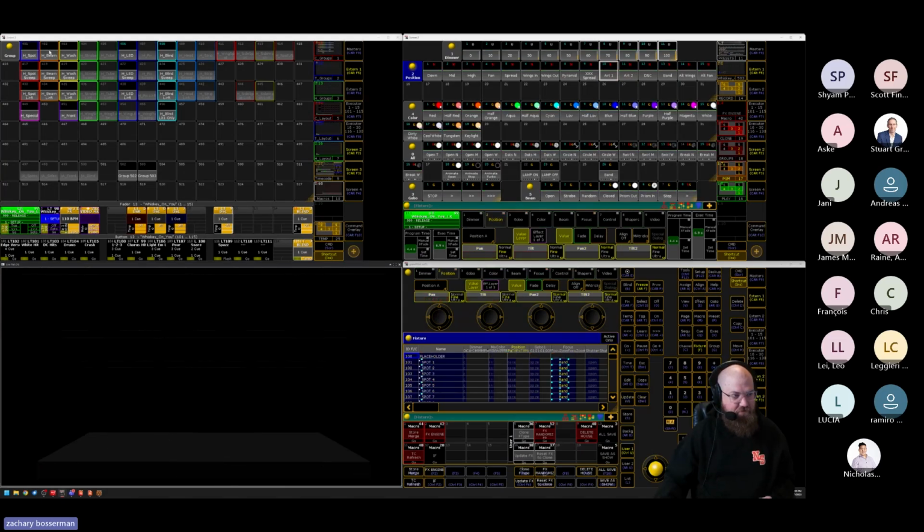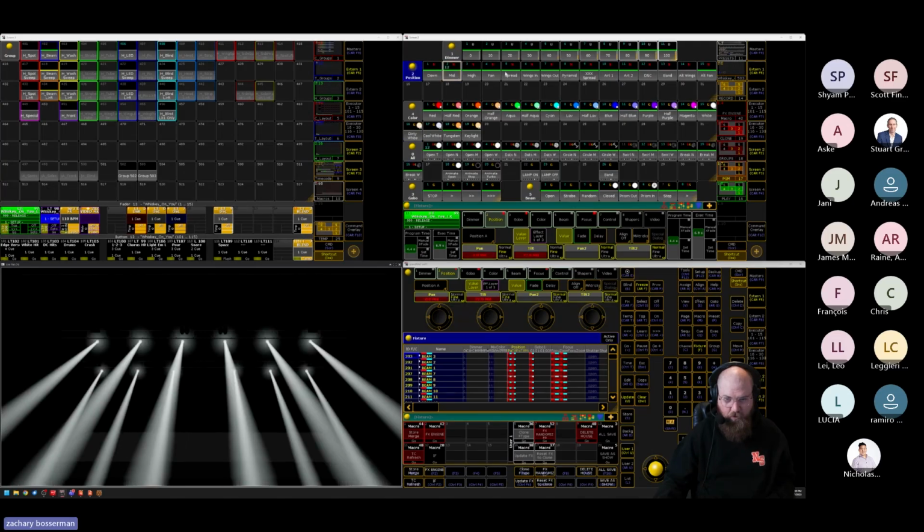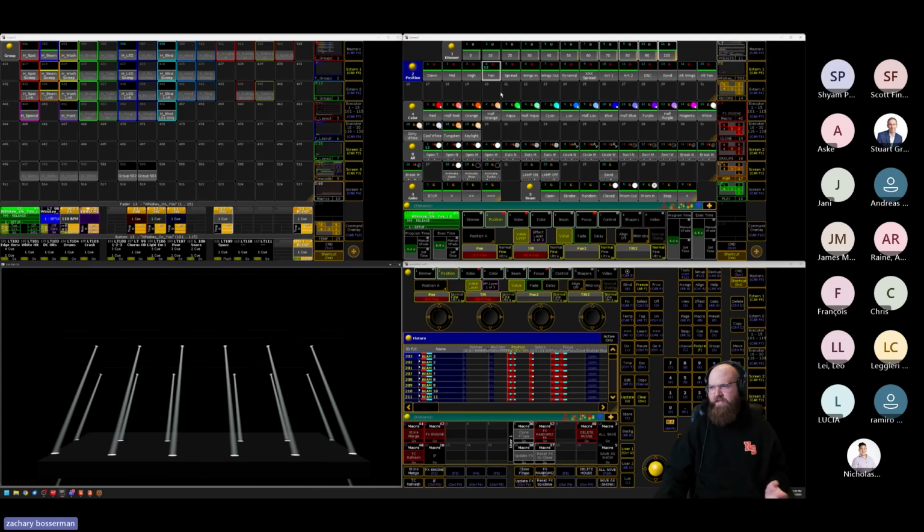We're going to check the beams the same way. Mid. Yep, those are all pointing the direction they need to. So wings in. Fan, I always check something that has a fan or has pan information in it, because sometimes pan needs to be reversed. Sometimes there's a single fixture that needs to have it done because it has some control mode in the fixture menu they set to invert the tilt 2 years ago for a corporate event and never changed it back.